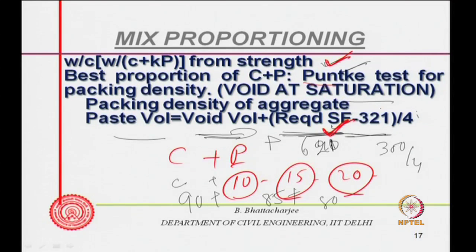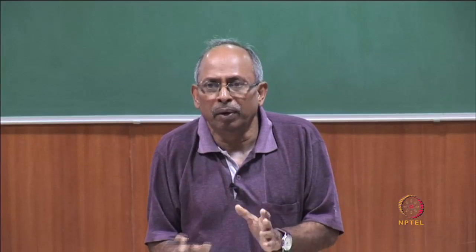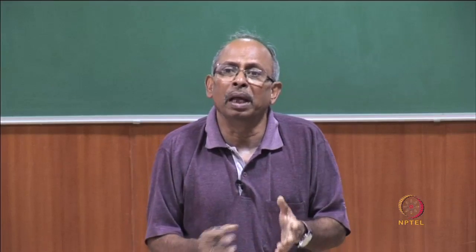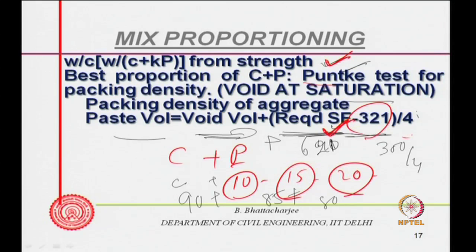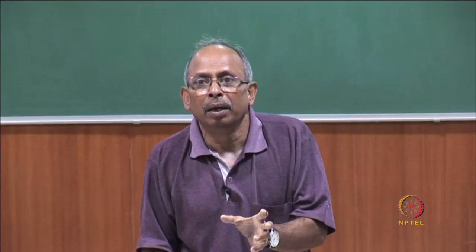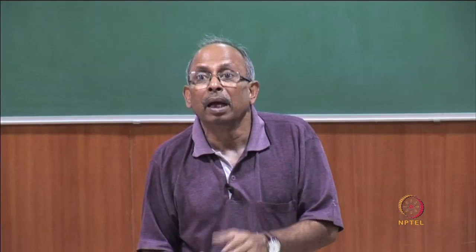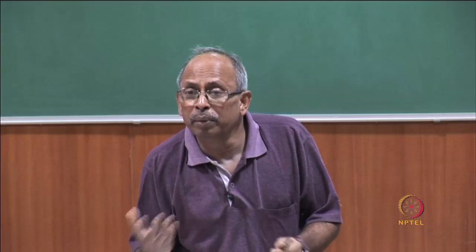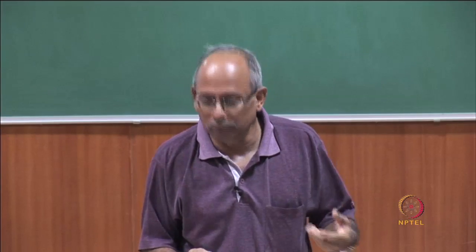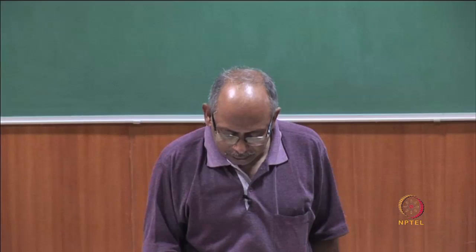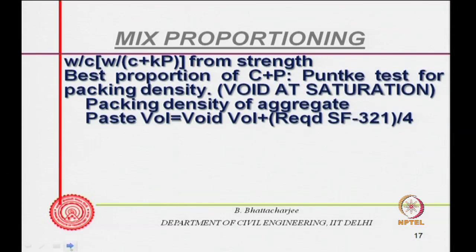The equation of course is empirical, so the units etc. are to be seen, but this equation may not be universally valid. Found out in one case, somebody else might find somewhat different values and so on, but at least the qualitative understanding is very clear. If you require more slump flow, more fluidity, then you would require more paste, and this is understandable from our discussion in different lectures.